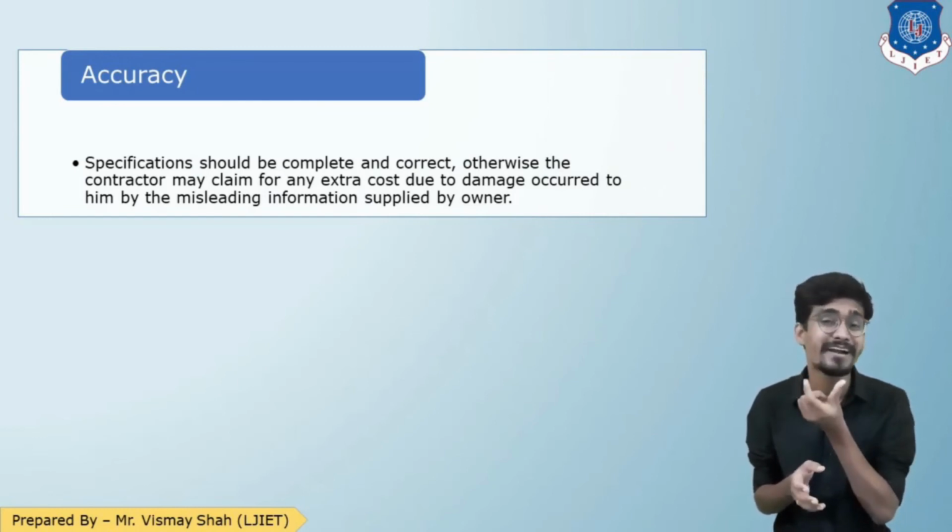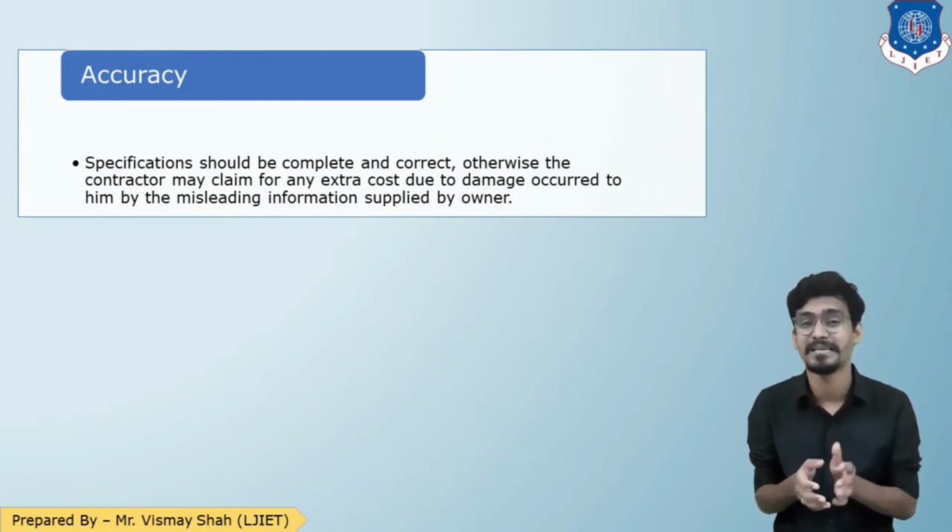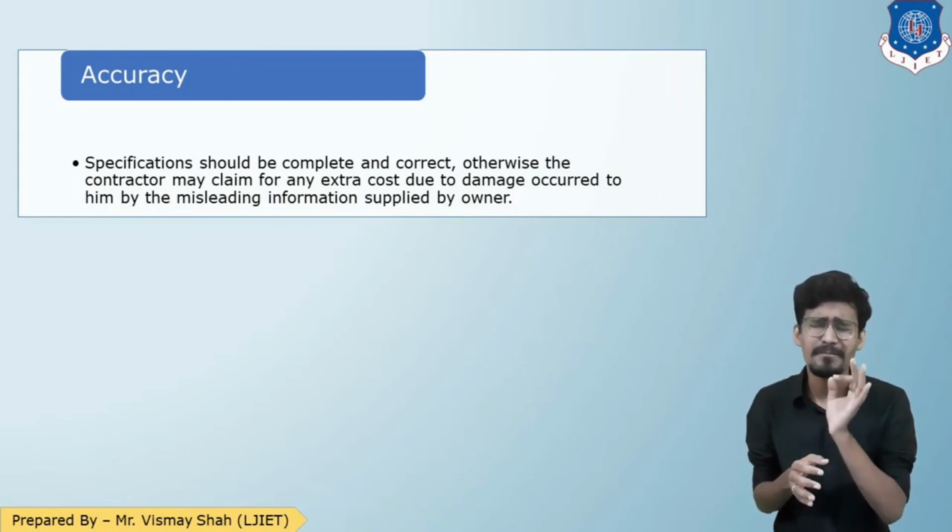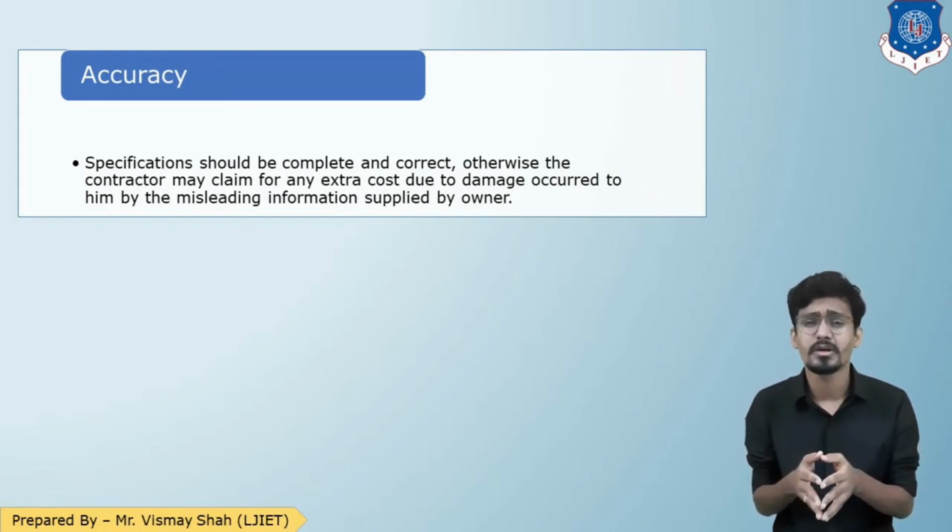Now you have only added "unobjectionable place", so the contractor will understand that he can neither throw the material on the road nor stack it on the adjacent plot. This is how accuracy works. Any minor misleading information will cost you very high.